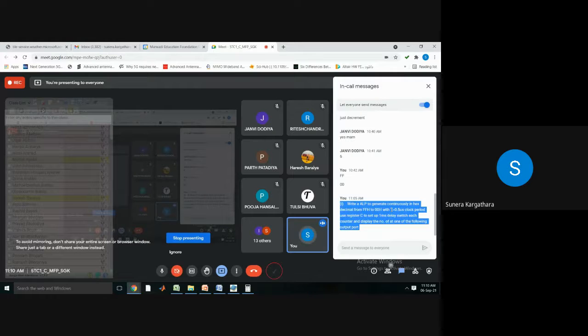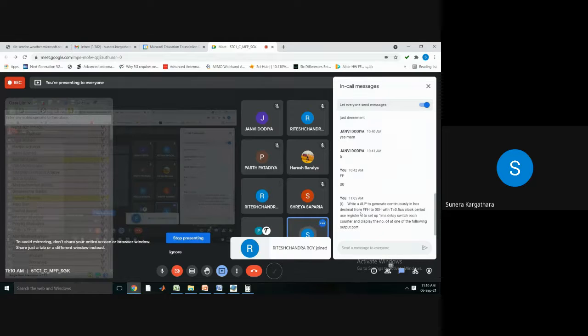So here we want to generate a delay of 1 millisecond, which is less than 1.8 millisecond. So obviously you can use the second method, the register method, and for that you require your F, and here sometimes F is given to you, sometimes directly T is given to you. Can you see here, student? यहाँ पे directly आपको T दिया गया है, right? That T is 0.5 microsecond. If instead of T, F is given to you, you need to find the value of T. So we have to provide a delay in between the count, and that is 1 millisecond. That you can do with the single register method, and that you will put in between the count value. So I hope this is clear.